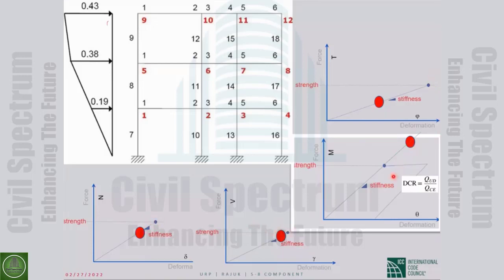For the deformation control parameters, we don't adjust the demand, but look at how much the demand is more than capacity. And based on the condition of the element and the performance level, the accepted damage is a coefficient times this, an m factor times this.